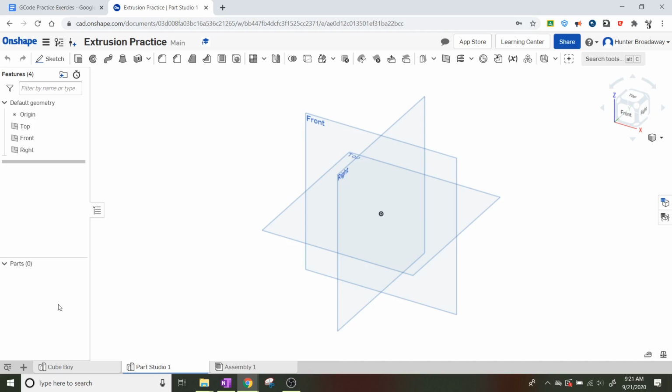So create the circle first. Click on the circle and drag it out. No, sir. Click on that. Now click on the center. Okay, you just unclicked circle. So now click on the circle and then drag it. Now click Finish Sketch. Okay. Extrude.